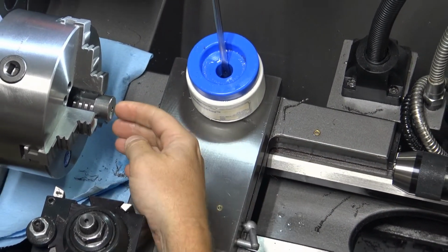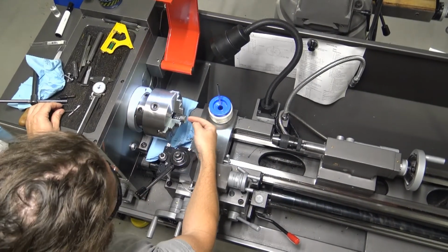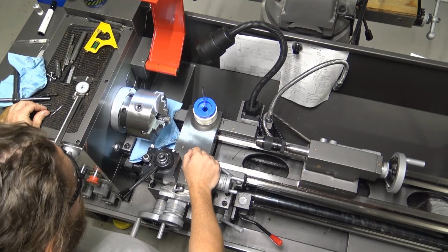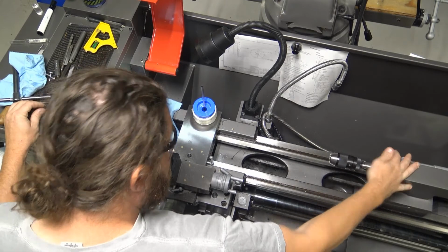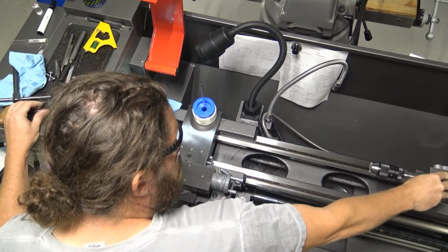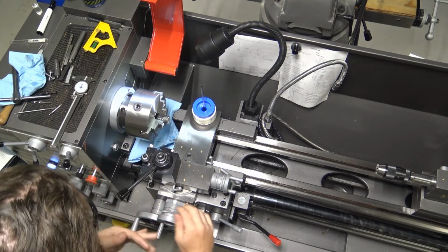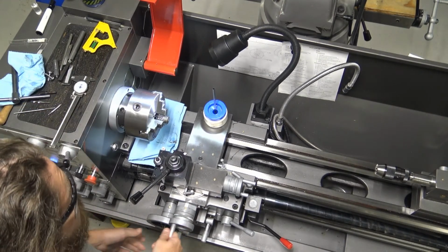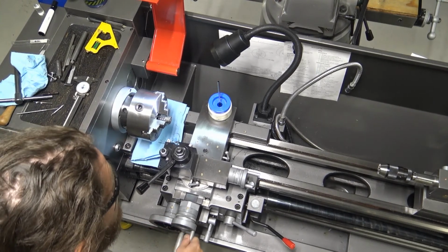Now this hole that we've reamed, we actually came from that side, we flipped it, and now it's nice and in line with our center of rotation. I'm not going to need the tailstock anymore, so I'll slide that out of the way. So step number 5 was to flip the part using the reamer.